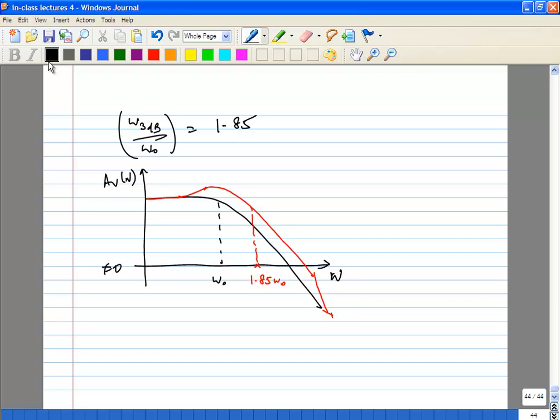So you have managed to get an increase in the bandwidth, but now you have a problem. Your magnitude response is actually peaking. What that means is for different frequency components you have different gains. You don't want that. It turns out in this case this is almost 20% peaking, so approximately 1.5 to 1.6 dB. There are a lot of applications where you don't want that.